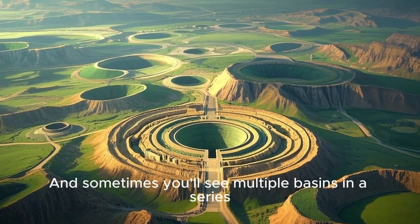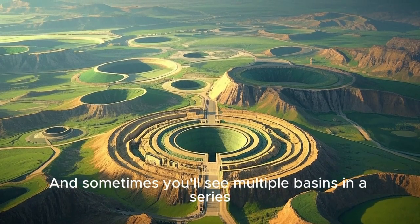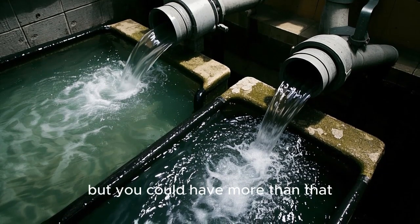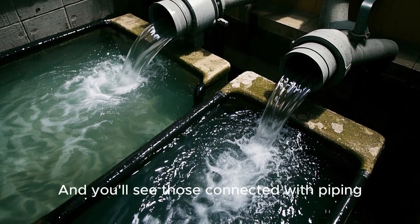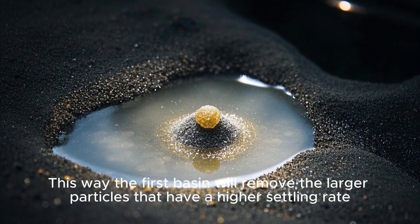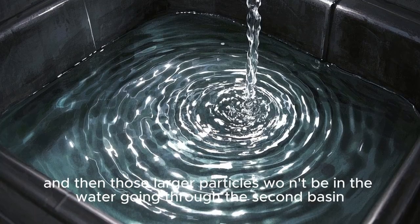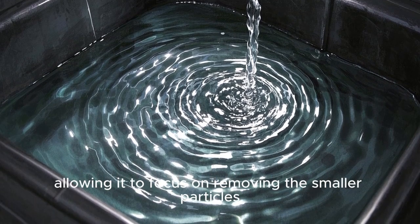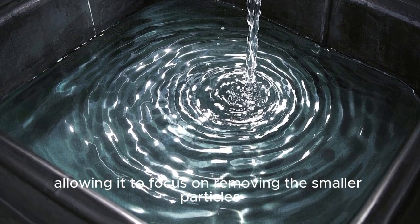And sometimes you'll see multiple basins in a series. Two is most common, but you could have more than that, and you'll see those connected with piping. This way, the first basin will remove the larger particles that have a higher settling rate, and then those larger particles won't be in the water going through the second basin, allowing it to focus on removing the smaller particles.